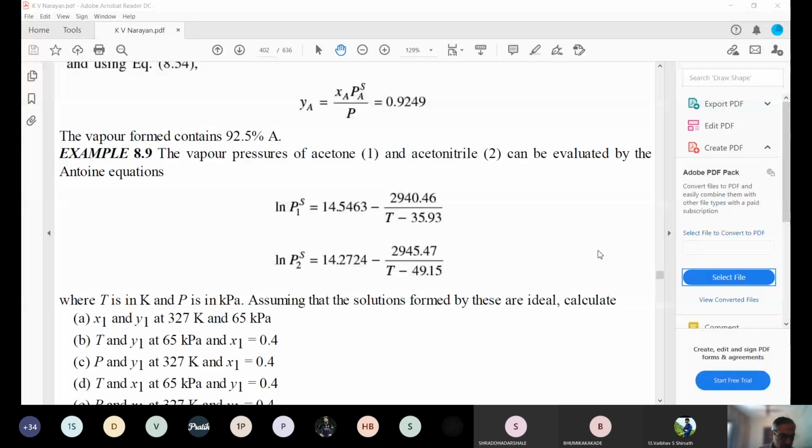समझ में आ रहा है? Because we don't know what temperature should be, we assume a certain temperature. Because the pressure should come as 65. ये calculate करने के बाद आपको आंसर चाहिए 65. Till we get pressure equal to 65, we have to keep changing temperature. समझा क्या?